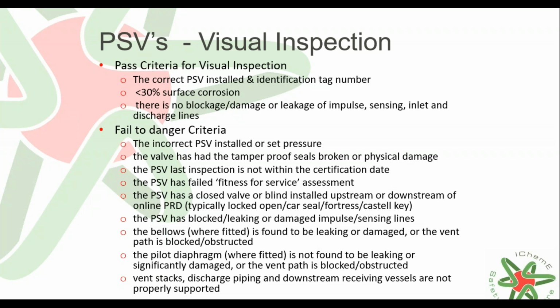And again, things like incorrectly installed PSVs, sometimes they might be found as part of the initial bring on of the PSVs, and I know that was done a couple of times within my experience where the PSVs, particularly the remote mounted ones, get removed as part of the campaign, get put back up again, and then sometimes they can get put in the incorrect location. So making sure they're correctly installed is critical.